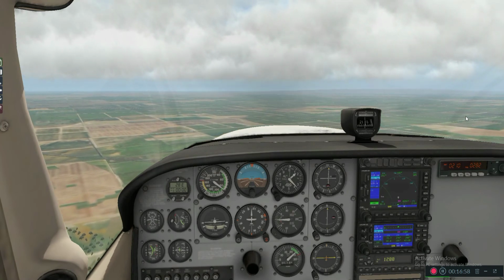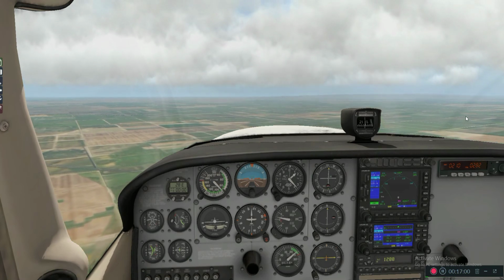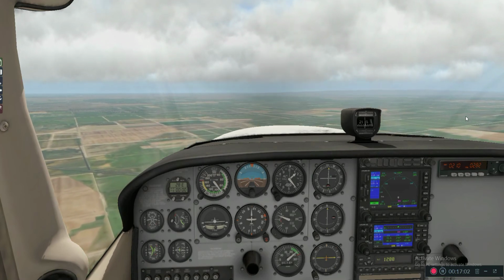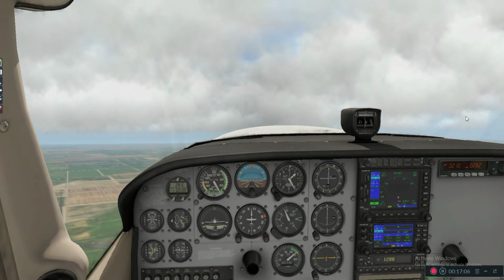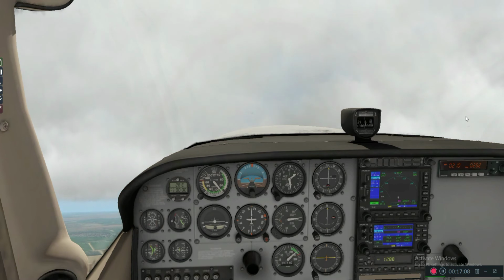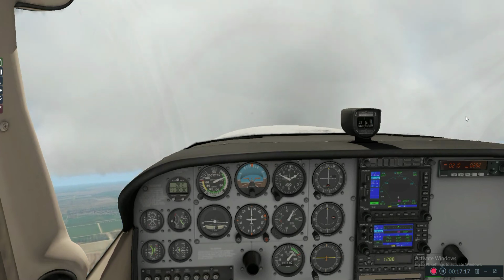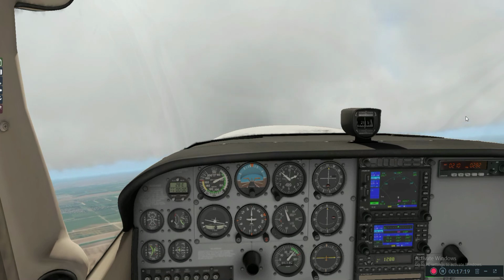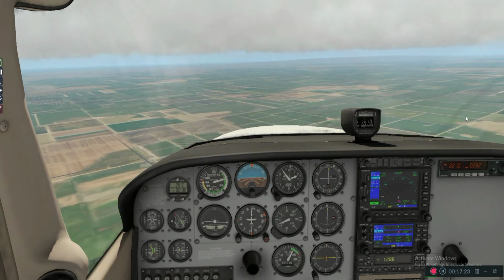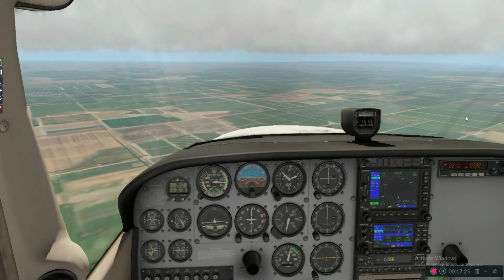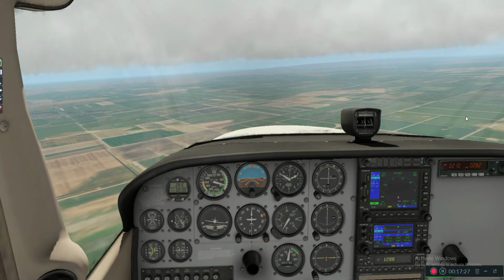So that's that left turning tendency of the engine. And you know, that's important, because in a real 172, that's something to think about. You know, if you're climbing, you're at a slow speed, you're at a high angle of attack, that's a significant factor. You see right here, see the ball going to the right? So you need some right rudder to correct for that left turning tendency. And that's why this is such a great trainer, because it's simulating these simple things that are important to learn for any pilot, but especially when you're starting out and trying to build these habits.